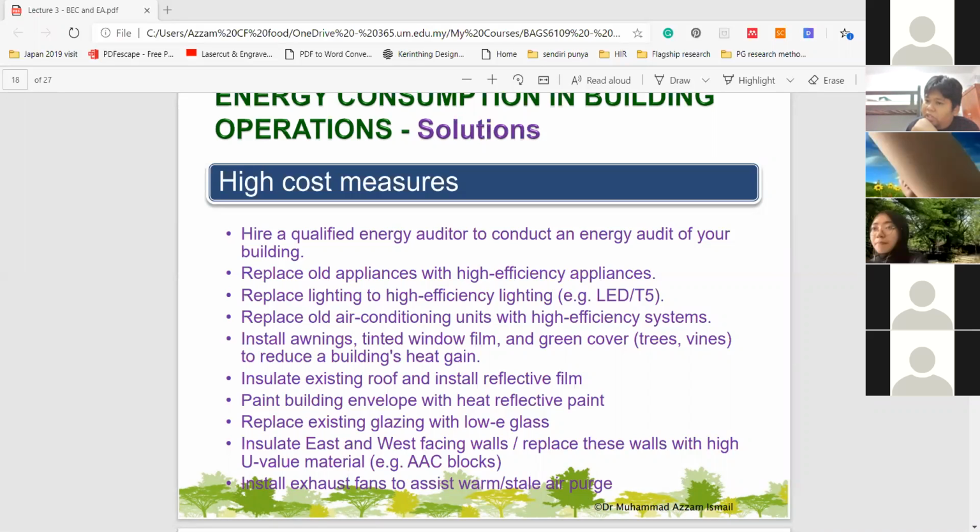So your corners, your window sills and whatnot, you can cut the blocks into shape, so you don't have wastages like what you probably have previously. Okay. So previously, as a building contractor, if you had to build a wall, you would probably be ordering a whole truckload of bricks, and then they come into the site, the truck, rather than in pallets. Okay, AAC comes in pallets, a very finite amount of blocks in a pallet.